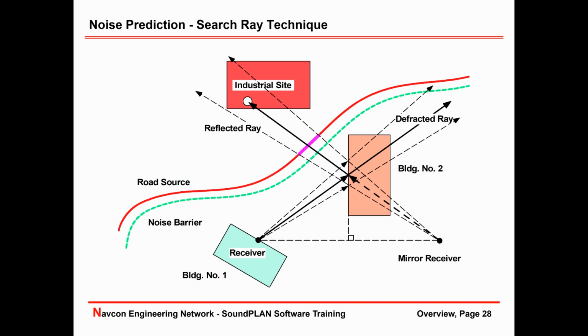or wind direction. And then after that path is computed, it notices that there is a reflection here. And then, of course, the program will create a mirror receiver and continue the path in this direction. So the incidence angle is equal to the reflective angle. And it continues and finds, again, new objects, new barriers, sources, and so on, and continues that path. There are certain criteria when to end, how many reflection orders, or how far the path has gone.